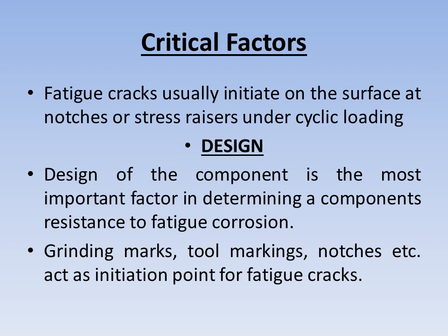The code lists the surface features that can act as stress concentration points and thereby the reason for fatigue cracking. These features become the crack initiation points also. Some of the features are mechanical notches, that is sharp corners or grooves, keyholes on drive shafts of rotation equipment, weld joint flaws and or mismatches, tool markings, grinding marks, lips on drilled holes and corrosion.